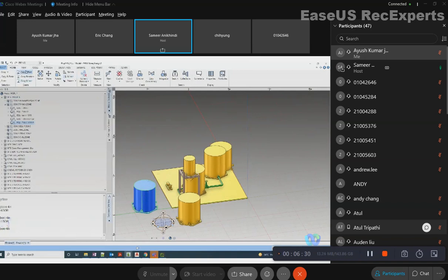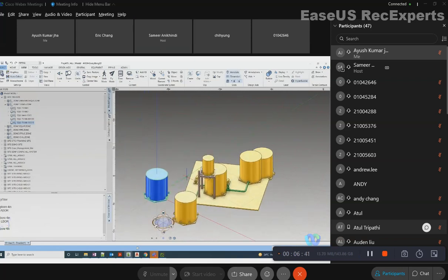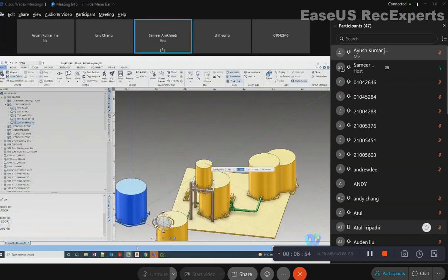So you can go to view current elements. So what happens is complete axis shift from that point to this point. Right. So this point temporarily becomes my origin until I shift back to my global origin. Now, for example, I do the ID command. Let me measure the top of the cylinder. So since my units are in meter, it is showing some value 4.6, 4.65 with respect to the temporary origin. This is my temporary origin.